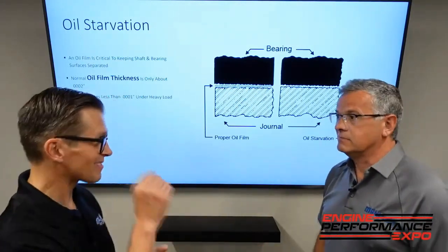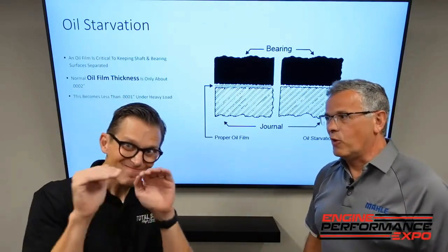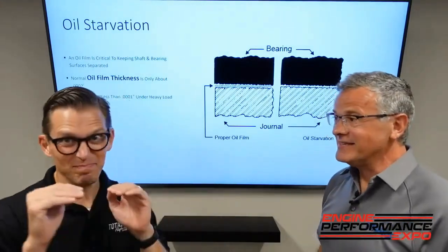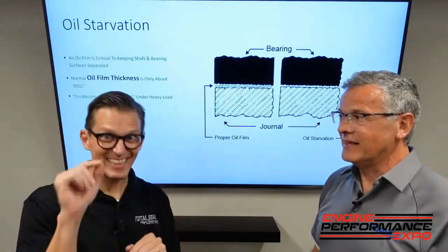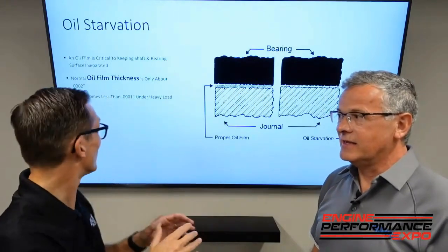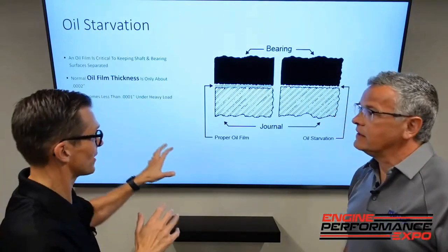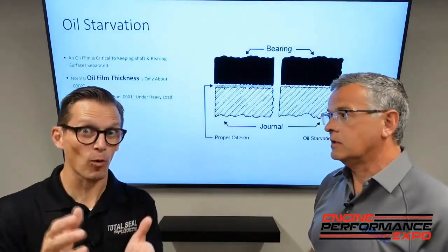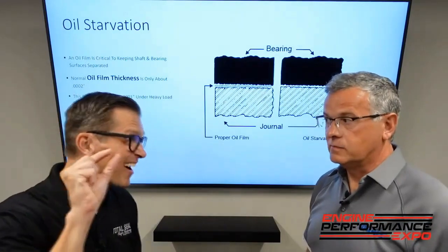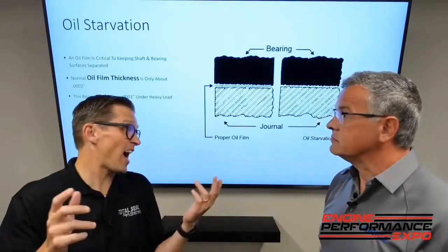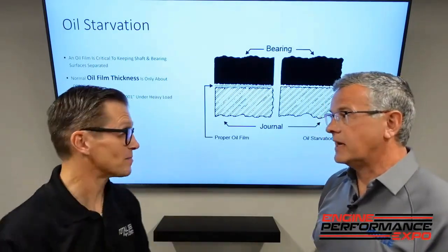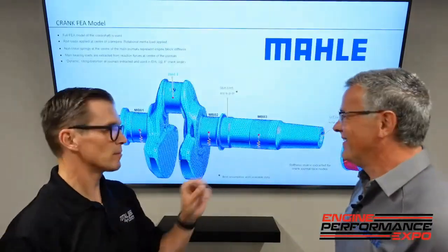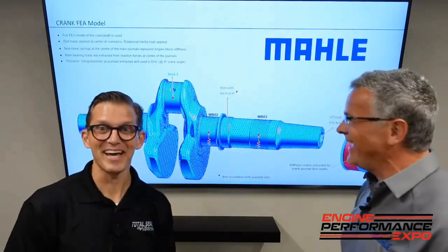Yeah, so that 1/10 is your shield. It's very strong, but very thin, so you have to maintain it with all the protection you possibly can, which is why alignment and cleanliness and all that is so important, because you have a very, very small margin of error, 1/10 of a thou. I can't see 1/10. That's pretty small. That's 100 micro inches.